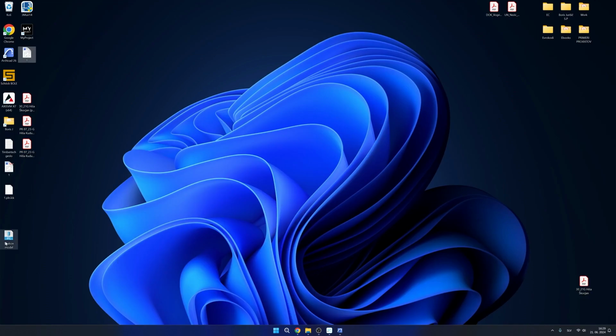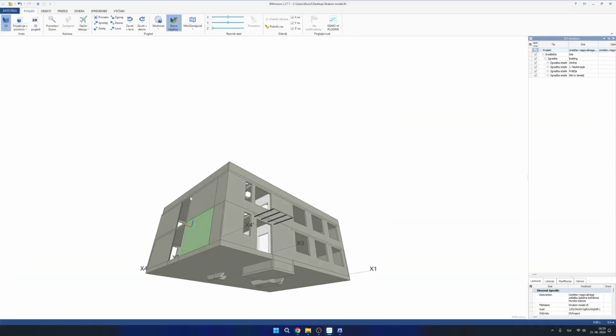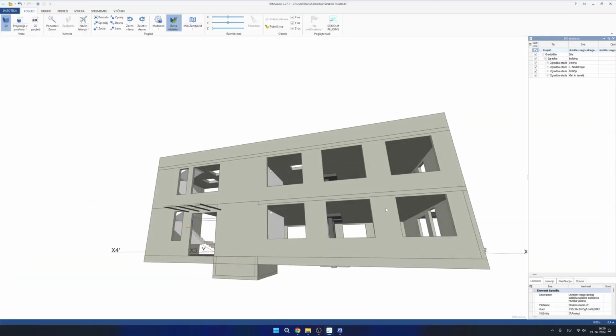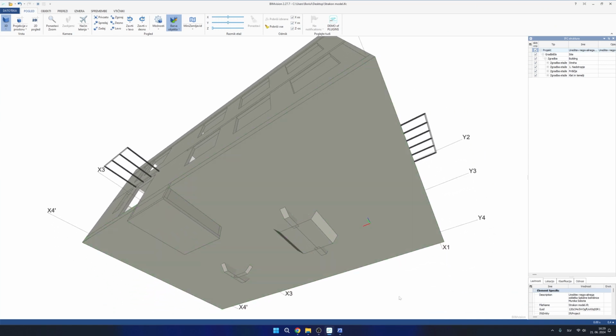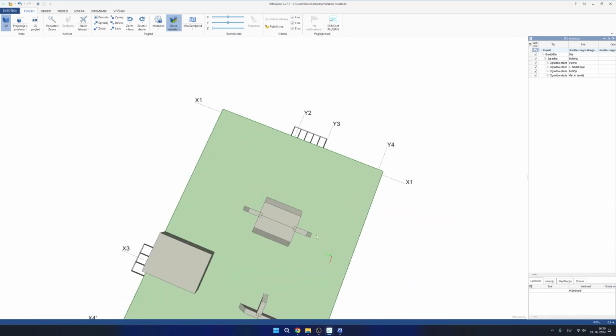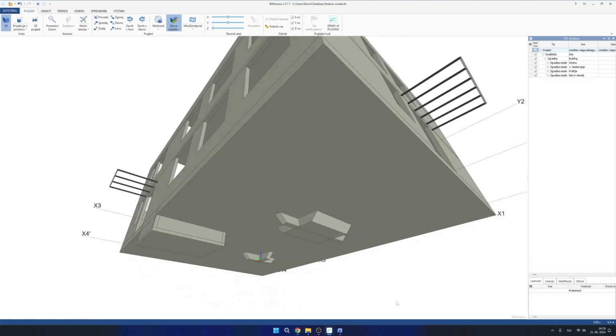Before sending it out, I will do a quick check. So here I just have an IFC viewer. Okay, I can see this model is pretty okay. But here at the bottom, I have a problem. Some of these foundations were not correctly translated.